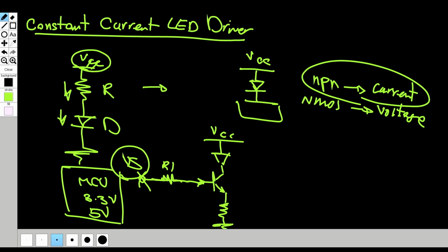Again, we can talk about it when we go through certain calculations, but you can find out that the base current has to be within a certain amount, so that the collector emitter current follows. There's that equation that follows that amplification because of the beta, the gain of NPNs. NPN transistors have a beta parameter, which is the current gain.